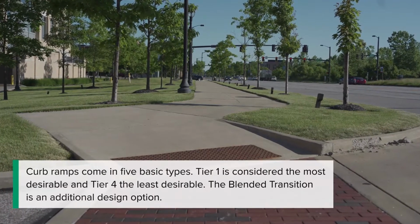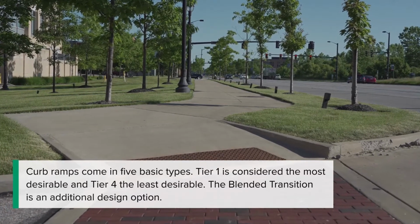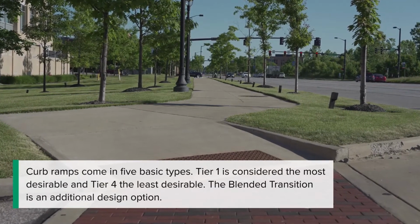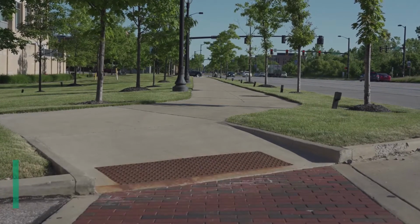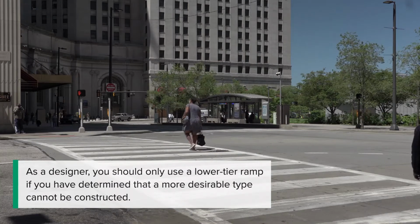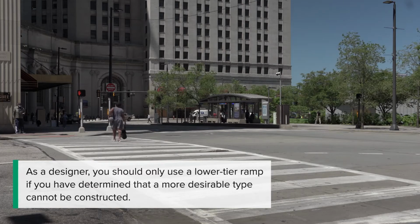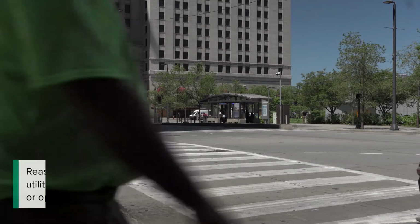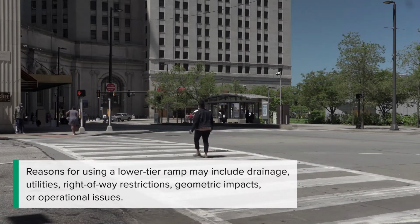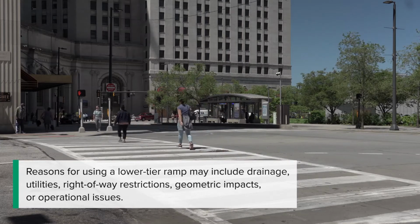Curb ramps come in 5 basic types. Tier 1 is considered the most desirable, and Tier 4 the least desirable. The blended transition is an additional design option. As a designer, you should only use a lower tier ramp if you've determined that a more desirable type cannot be constructed. Reasons for using a lower tier ramp may include drainage, utilities, right-of-way restrictions, geometric impacts, or operational issues.